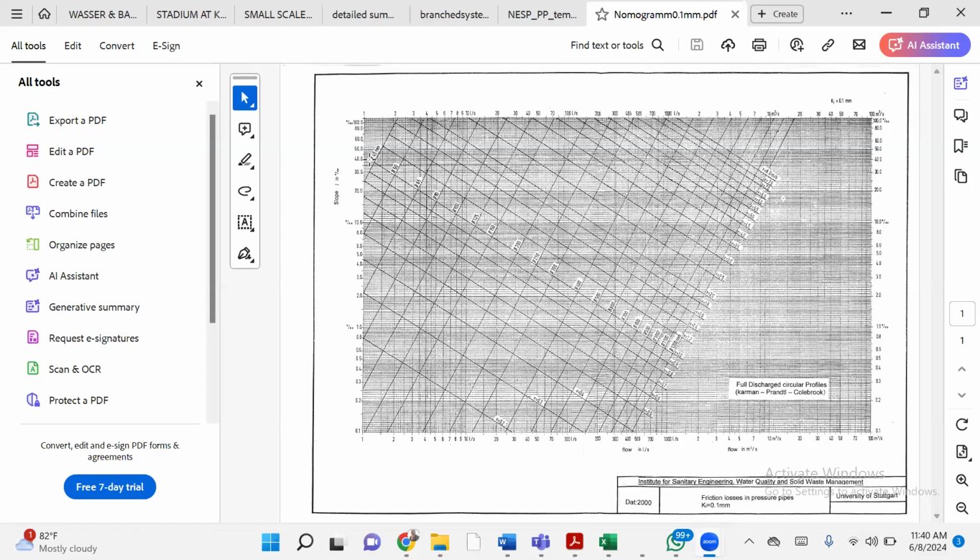Okay. Are you a civil engineer? If you're a civil engineer, you will discover that you cannot use 12 mm to do a column. You cannot, because there's a minimum reinforcement requirement for a column, based on BS 8110. So for every design, there is a minimum reinforcement.